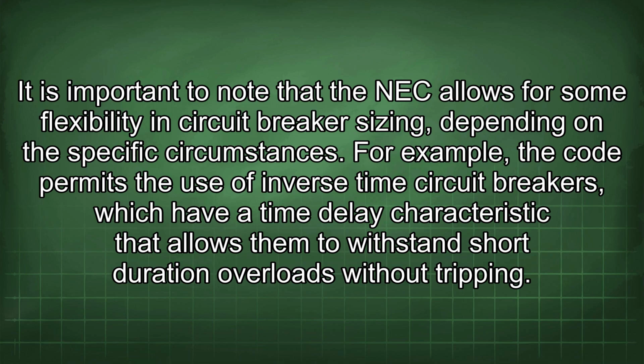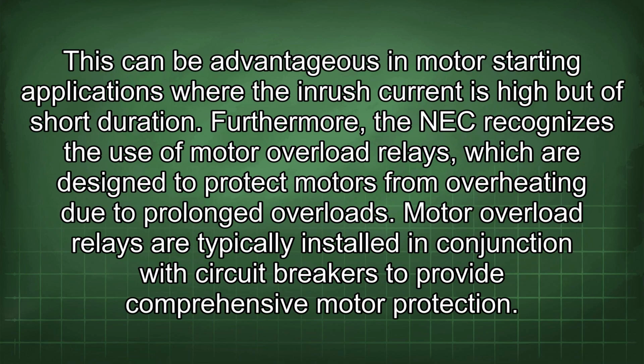the specific circumstances. For example, the code permits the use of inverse time circuit breakers, which have a time delay characteristic that allows them to withstand short duration overloads without tripping. This can be advantageous in motor starting applications where the inrush current is high but of short duration.